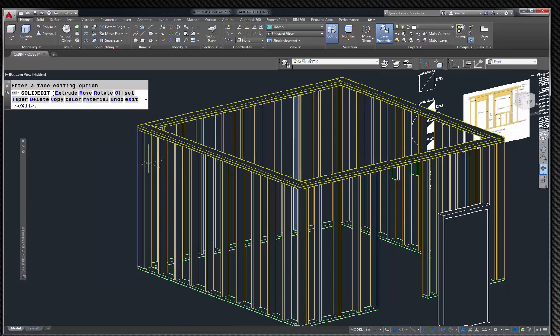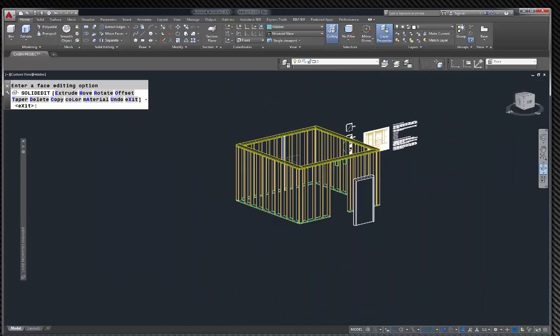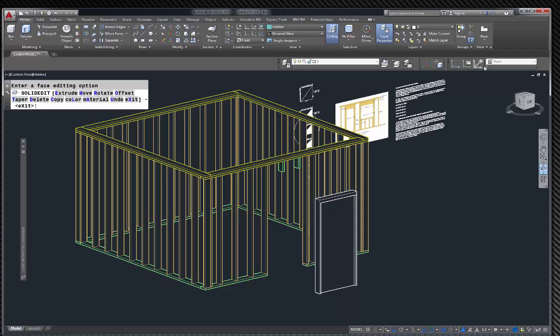And then I need a 2x6, so I'm going to go in here and go to home. Go to world, great. And I want to draw a 2x6 on edge vertically this way. So it tells me I want to be in the left, so I'm going to grab that and go to left. I'm going to go up to my box, over here, go length. Make sure, and notice it's staying for some reason in ortho this time.